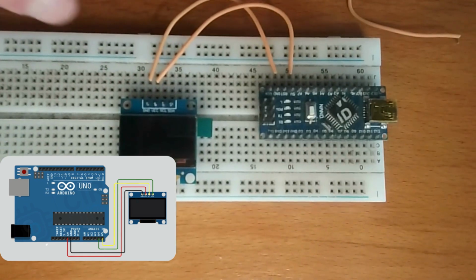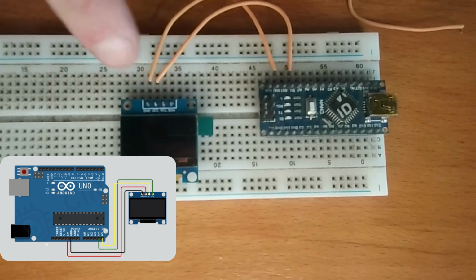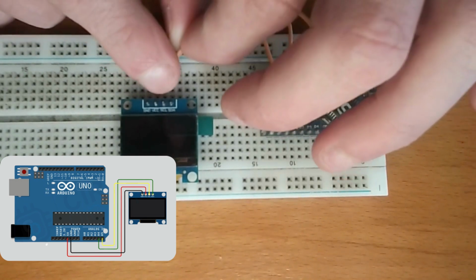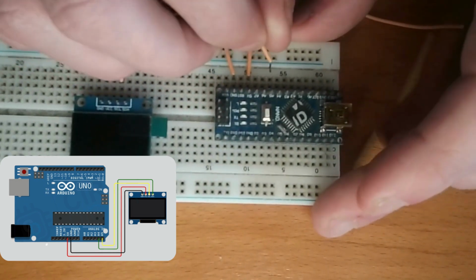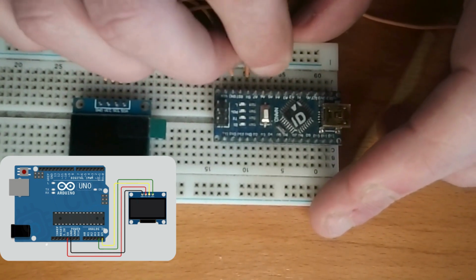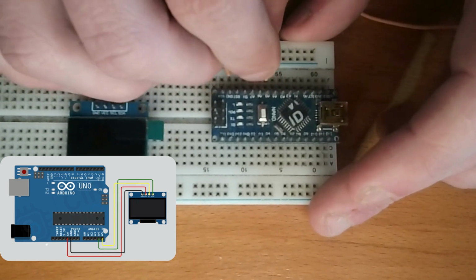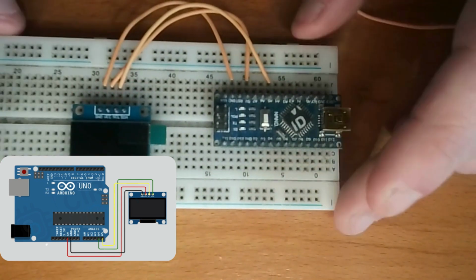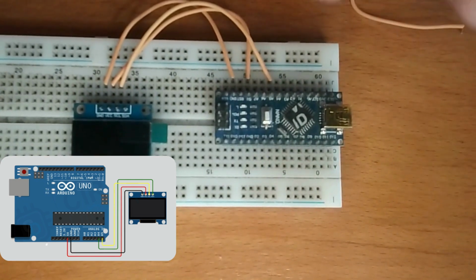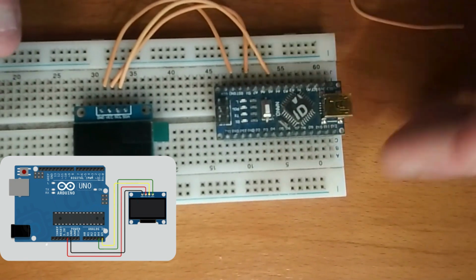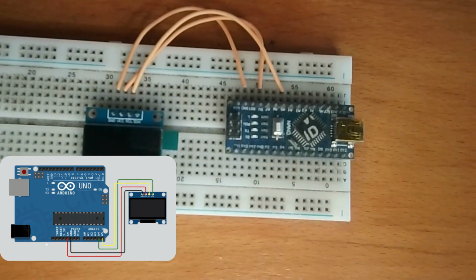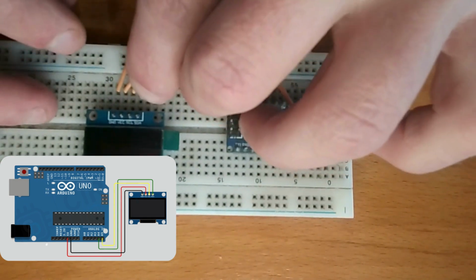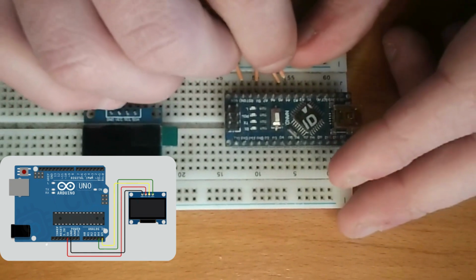So now we'll go ahead and connect up the SCL pin, and the SCL pin is one of the pins that will help us communicate with I2C to the OLED display, and we're going to have to connect that to A5 on the Arduino. And why we connect to A5 specifically is because A5 and also A4 are the pins that provide I2C communication with the Arduino. So it's important that you actually connect this way because it won't work with other pins because they don't have I2C on them. So then SDA will be connected to A4 on the Arduino. So we can go ahead and connect that on there.